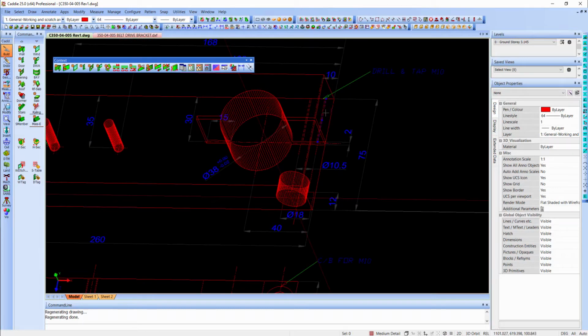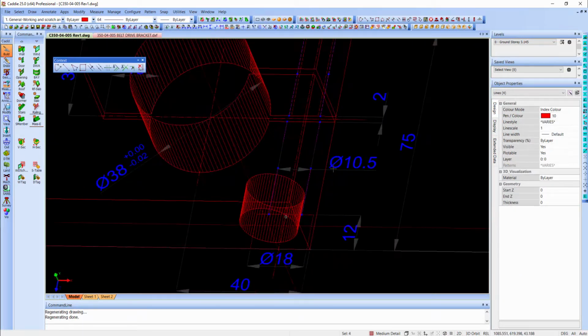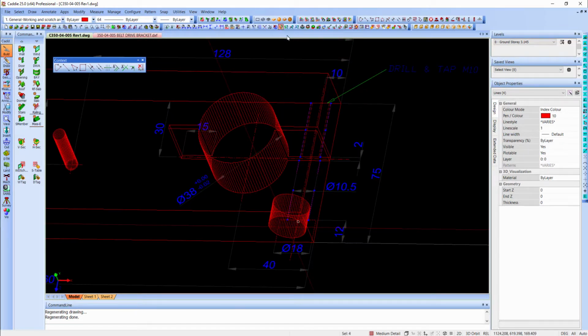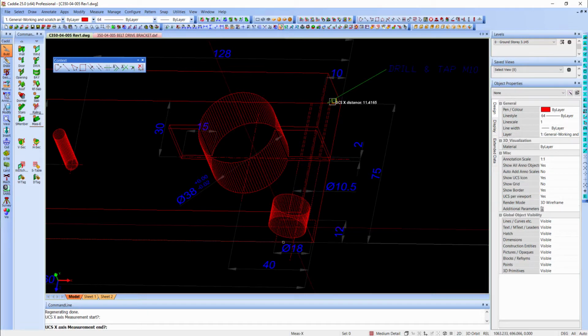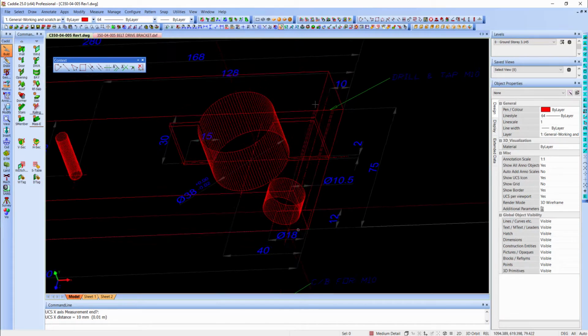Now for the next section, we do exactly the same. I'll just set it here to wireframe so you can see those are normal lines, and we're going to cut it through the whole section of this body. Measure that, that's 10 millimeters diameter, so it's a 5 mm radius. Our UCS is already in the correct position. All I have to do is now create the mass element.